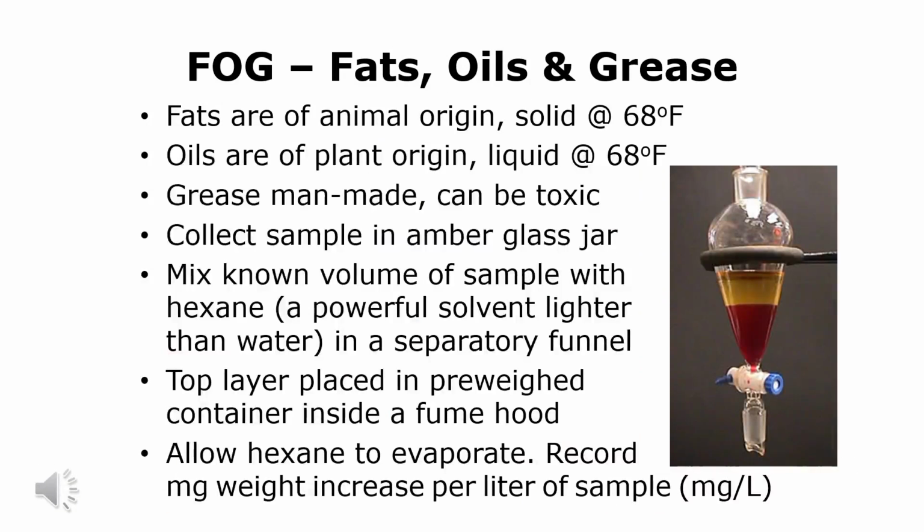FOG, also known as fats, oils, and greases, are similar in that they are all lighter than water. Fats and oils are two types of lipids. They are chemically similar in that they are lighter than water, are attracted to other lipids, but are repelled by water. That term means oleophilic and hydrophobic. FOG samples are collected in the field with dark glass jars because FOG concentration is sensitive to sunlight.